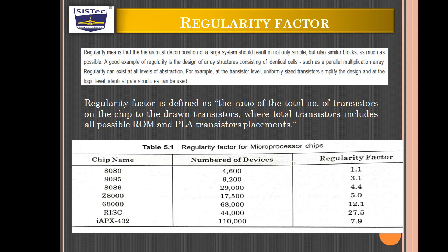Regularity is defined by a regularity factor, which is defined as the ratio of the total number of transistors on the chip to the drawn transistors, where the total transistors include all possible ROM and PLA transistor placement.